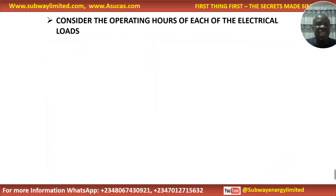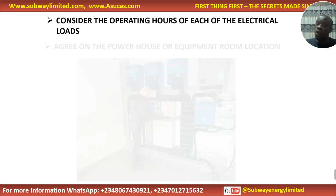So consider the operating hours of each of the electrical loads. We said this before: the operating hours of the electrical load affect the size of the solar system. So you have to consider the operating hours of each electrical load. Document it.